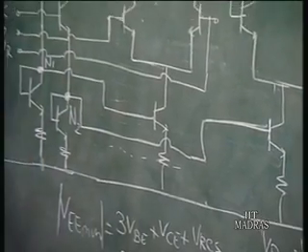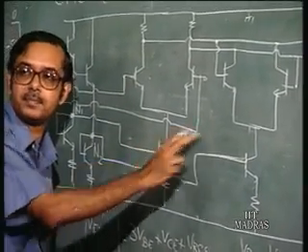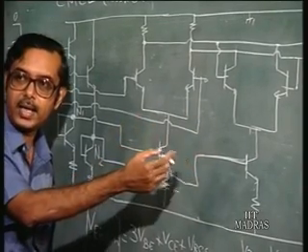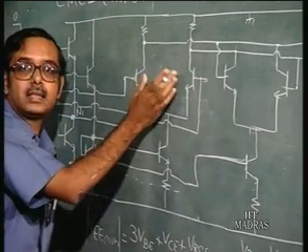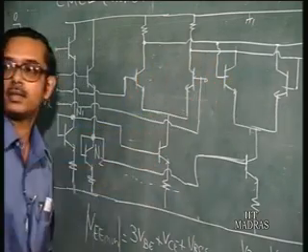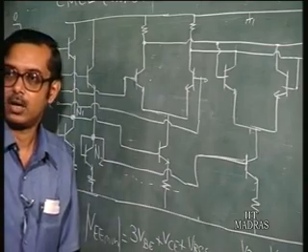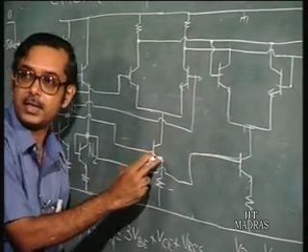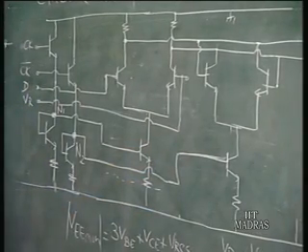Basically what we want to say is, in the previous circuit you had an emitter coupled system here, to which you were feeding the clock and clock bar. Depending on whether the clock is high or clock bar is high, either the left part or the right hand side stack of the emitter coupled structure in the upper stack was on. Here, instead of having an emitter coupled structure at the lower part of the stack, you have an arrangement like this.